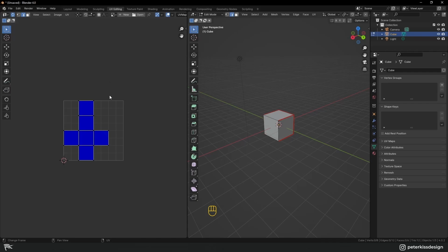When I select some vertices and move them around, it changes color indicating we have stretched UV. What it really means is that in 3D it is a perfect square, but in 2D it's mapped differently and will cause texture deformation, as it will try to fit this stretched shape to a square in 3D. Our target should always be to unwrap with minimal stretching.